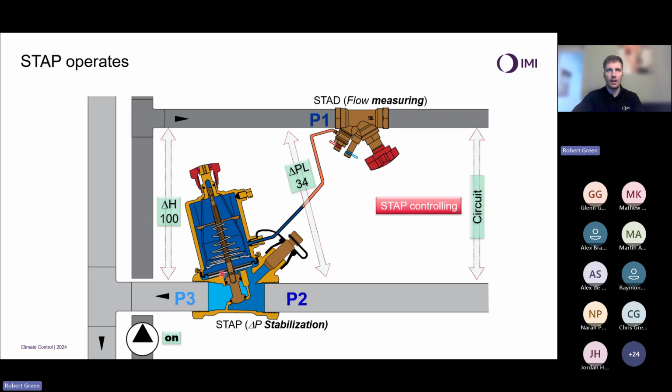And this valve is shutting down to take out these differences and maintain a quasi-static differential pressure in the circuit. And that is the essence of how a DPCV operates. It's continually opening and closing as my differential pressure is changing to maintain that stabilized differential pressure downstream.